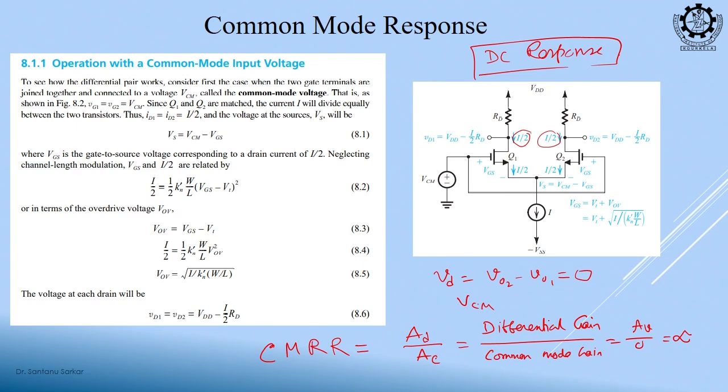What we can calculate is that this VCM, suppose this is increasing. So, if you do not have this I, what would happen? Suppose this I is not there, and now you are increasing VCM, what will happen? This I will increase, right, both of the I will increase, branch current will increase, and if it increases, the output level will also fluctuate, because you are subtracting more current.